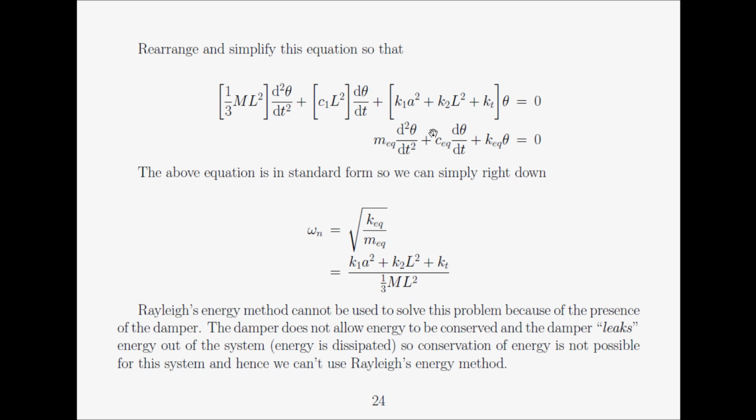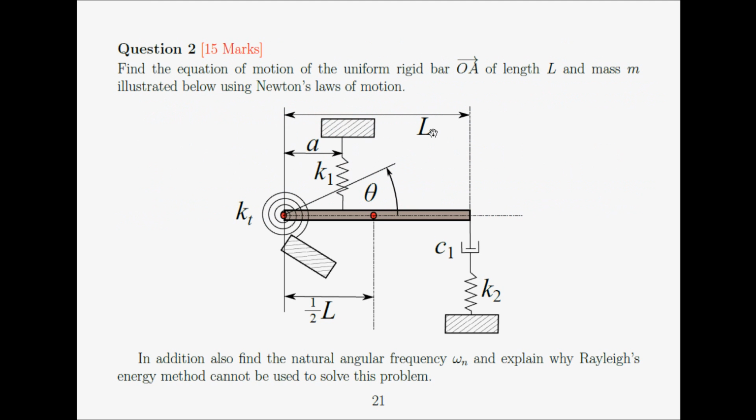And that concludes the calculations for question 2. So just to quickly sum up, we have a system, we use various geometrical concepts and ideas. We work out the deflections for the springs and the dampers. If there's a deflection, we take the derivative, we work out a velocity. Therefore, we work out the retarding spring force and the retarding damper force. We say force times distance, that will give us a torque. We add up the torques, that will give us the resultant torque. Then we apply Newton's second law. Torque resultant is mass times angular acceleration.